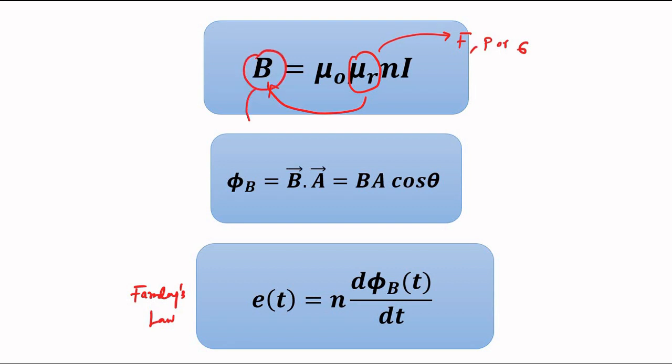Change in magnetic flux density causes a change in magnetic flux, and then change in magnetic flux contributes to generation of EMF, which is a voltage signal. With the help of suitable signal conditioning techniques we can convert it into current, and suitable amplification and linearization procedures are used, but that is a different thing. But we are getting a measurable